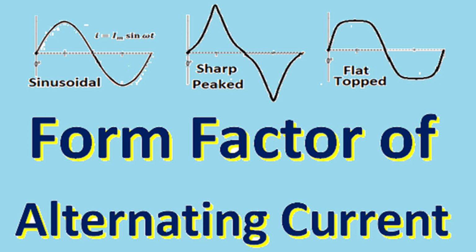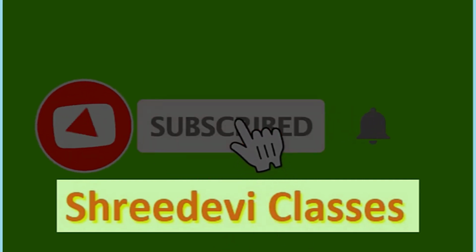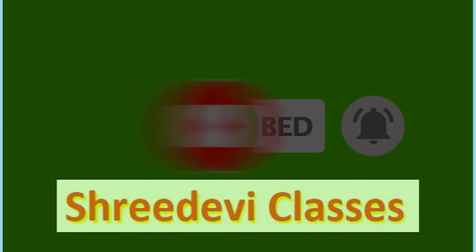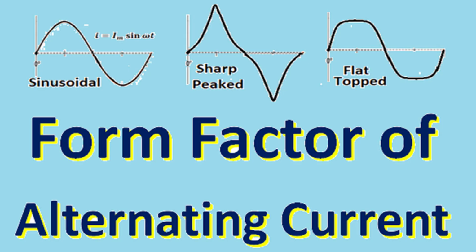And when form factor is higher in a thyristor circuitry output, we have to derate average current rating of thyristor, because heating is produced by RMS value and we are having output in terms of average value. And if duty cycle is such that form factor is higher, it means for same average current we are producing more heating to the device, so we have to reduce current rating of such thyristor.